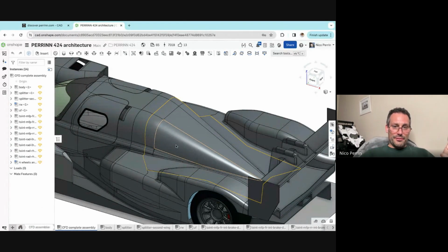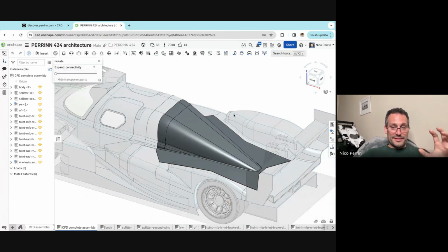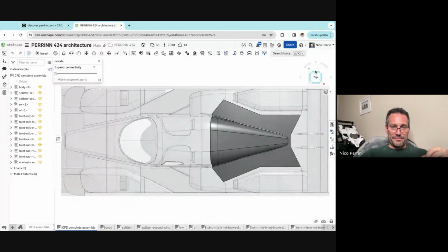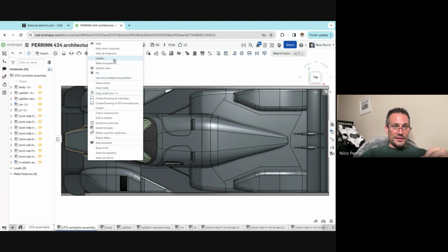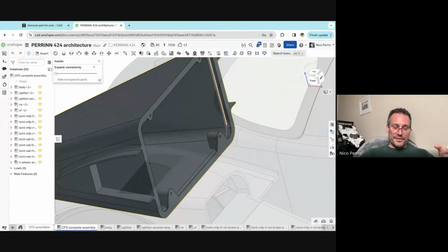I didn't have to, but I wanted to have a first idea of where we're going to split the panels. This is for a reason, in terms of practicality. I wanted to understand what sort of accessibility we would have when we remove the top panel, which we know is an easy panel to remove, because that will guide where we have some of the connections for the battery, for example, to recharge. You can see that we know exactly some parts like the crash box. You can see it's fairly detailed. In fact, in the crash box here, I put some locations for the mounting itself.